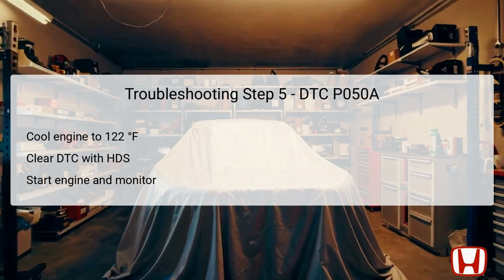Following the cooling period, clear the DTC using the HDS, effectively resetting the system. Once cleared, start the engine and allow it to idle for at least 10 seconds. Throughout this period, monitor the onboard diagnostic status for DTC P050A. If the system indicates a failure, it suggests that the problems persist, justifying further investigation. Conversely, a pass indicates the issue may be intermittent or resolved temporarily.